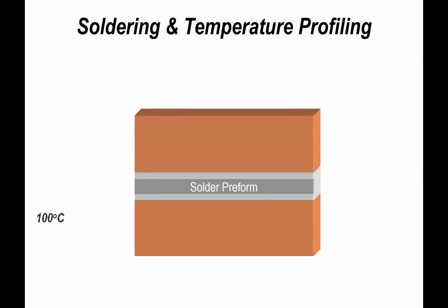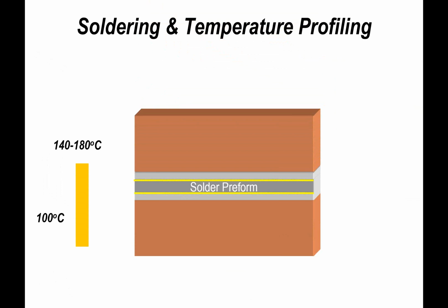Slowly we heat up that whole structure, and depending on the flux technology and the solder technology, tin lead or lead-free, there'll be a reaction with the fluxing material to aid the soldering operation for whatever surfaces we're working with. But if you're looking at more exotic materials, or stainless steels or Kovars, materials which historically can be more difficult to solder, then we may have to look at a slightly different direction.